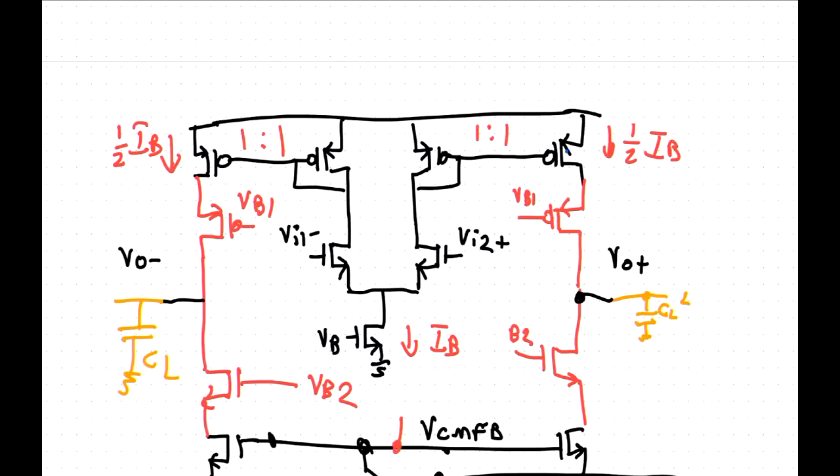And it especially depends on the K value, and also on whether you go into weak inversion. If you go into weak inversion, then the GM is just proportional to the current, and there's nothing you can do. So going into weak inversion is not a good idea, because then GM for these two is going to be the same, which means the noise contribution for these two is the same. So it's much better to keep these in strong inversion. This one is good for weak inversion because you have high GM for the amount of current you have. So that's good. But this one here shouldn't be.